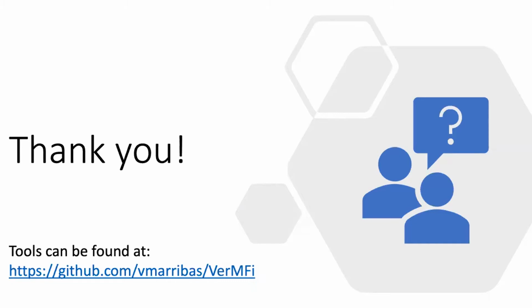While waiting for the questions, maybe I will ask something to bolster the tool design, right? We discussed yesterday the importance of flexibility, and also different design methodologies. How flexible are these tools to verify different design methodologies? For example, I'm asking for both Silver and the fault tool. There is a multiplicative masking scheme, in addition to the Boolean masking scheme, or for faults, we discussed redundancy using error coding, or complete redundancy of the whole block. Can we verify these also using such tools, or their extensions, for example?